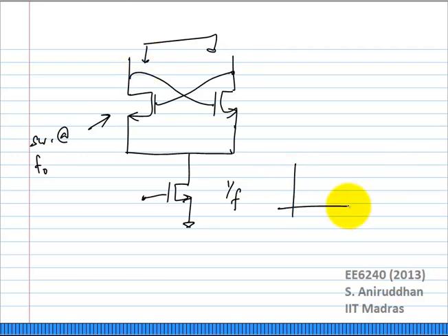Okay, so remember, if I have around DC here, if I look at this point, I should actually see something like this. Okay, so definitely that is one possible explanation for the existence of the 1 over f cubed region. First, the bias noise gets upconverted by the switching pair, then it gets multiplied by the frequency response of the tank to give you the 1 over f cubed region. Okay, let us suppose that this is one possible mechanism.